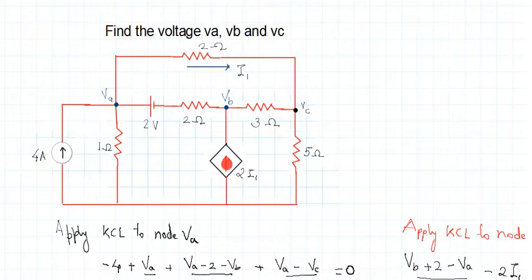And what type of current source is it? Is it current controlled or voltage controlled? This associated parameter will help you to identify whether it is a current controlled current source or a voltage controlled current source. Here the parameter is 2I1, and that tells us that this is a current controlled current source. So first you analyze this. Somewhere I must have I1 in the network. So here I1 is shown to you. I1 is the current through the 2 ohm resistor.